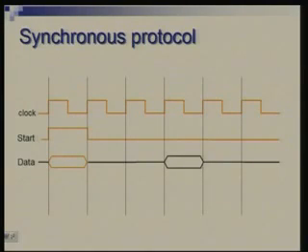In this case, all events will get timed by the clock. I am trying to show, let us say, the rising edge of the clock as the active edge. So all changes will occur here. Somewhere there has to be an indication that this is the first cycle where the transaction begins. So I am showing it with a signal called start, and the address will first of all be put on the bus.